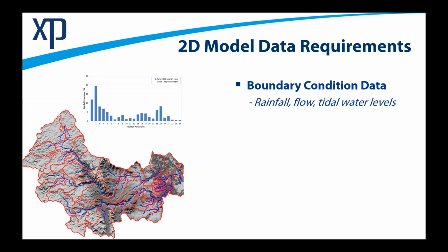Yeah, so for your rainfall, we just need your coordinates and you can send them through to XP and you can get your rainfall data generated for you based on the BOM website's IFD charts. So it's really quite simple and easy these days just to get your rainfall into the model however you want. There are several different methods and we might touch on those when we go through the example: what sort of rainfall and how you want to bring it in, rainfall on grid or a traditional hydrological approach.